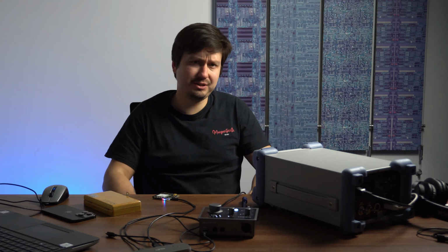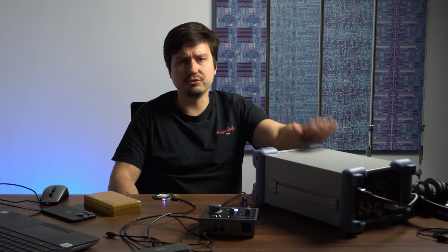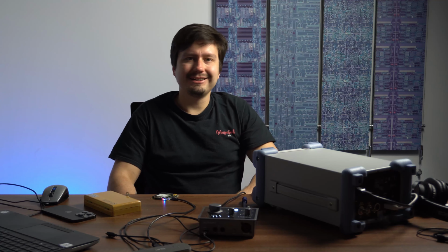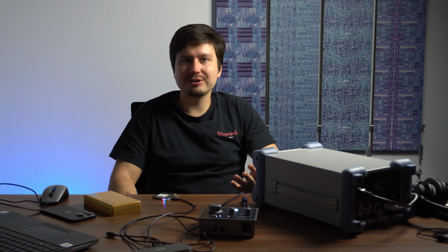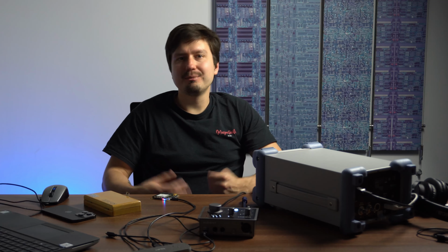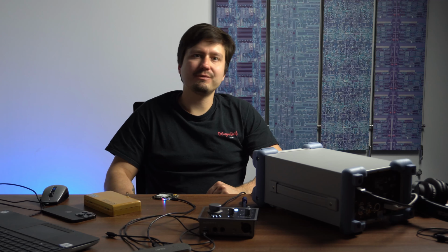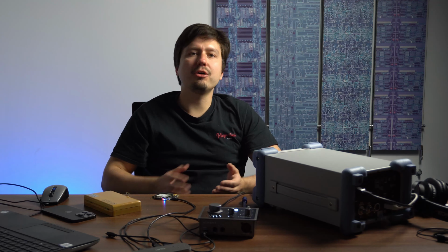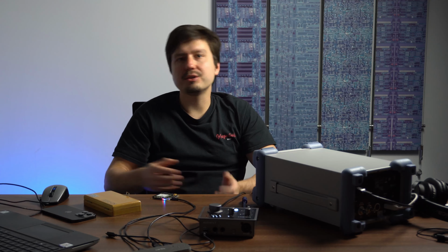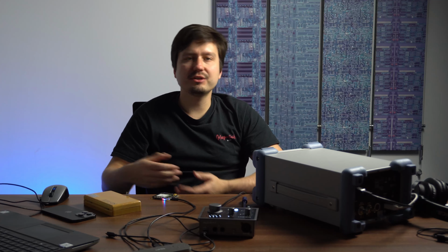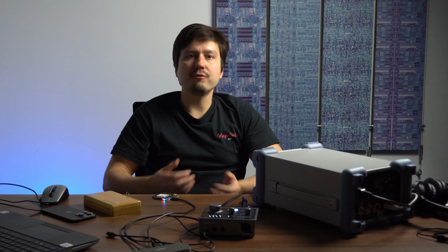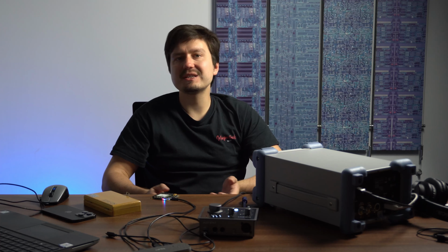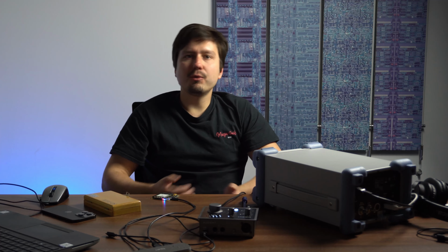Because if you pass EMC, then you don't need to do any of this. But unfortunately, or fortunately for me, because it keeps me employed, most products don't pass EMC first time. So this is why we need this equipment, and this is why we need this setup. Going out to anechoic chambers and test facilities such as Intertek or UL is always a very significant cost to the business. So you really want to minimize the amount of times you do that.